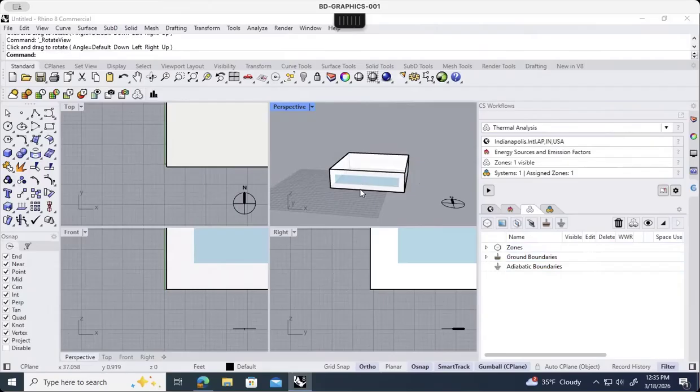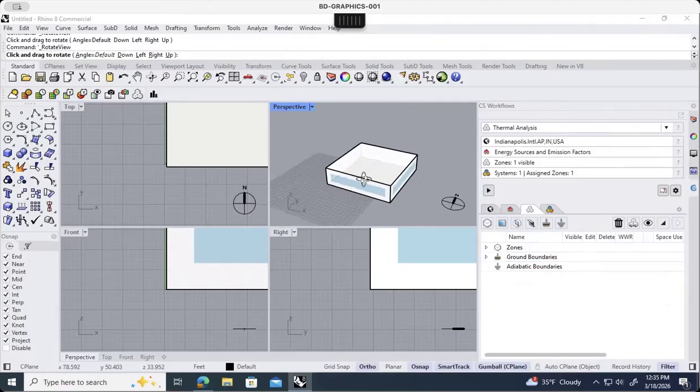Let's say I'm modeling just one floor of a multi-floor building. Maybe this is the ground floor of a five-story building. And by that definition, I just want to look at the thermal zone of this first floor, and I don't want to assume the subsequent floors. Moreover, this would not be a roof plane in that case. It would actually be an adiabatic floor assembly. And by adiabatic, just meaning that it's thermally inconsequential.